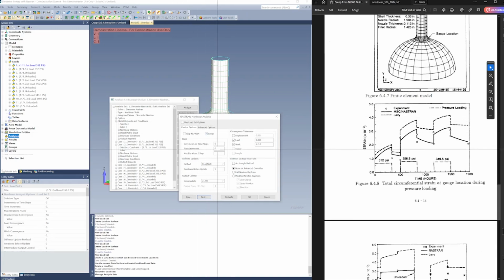We'll see we'll now have the options for time increment. And if we can then go over our plot, this is where we're going to refer to our creep setup here. So it's not exact here. This kind of looks like this runs for 1, 2, 3, and maybe a third. So 333 hours. I'm going to put 333 in here. Now this is going to be a time increment. These units are going to be in hours.